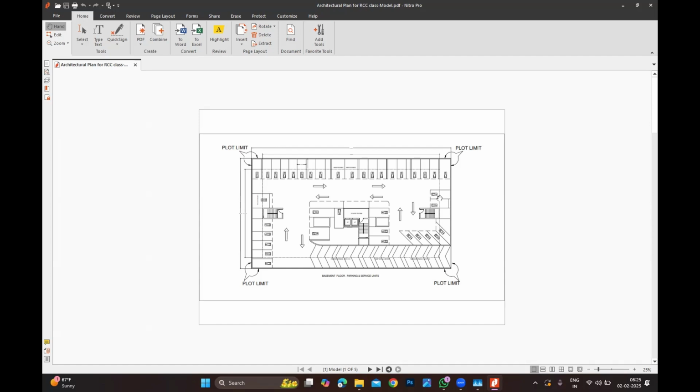You need to see the majority of the typical floors. So you need to group in such a way that you know what the majority typical floor is. Note down this point, this is more important. Most people don't know how to place the columns, how to set out the columns. That is a scratch. If you don't know how to set out the column, then there is no point proceeding further from a design point of view. You understand what I'm trying to say?